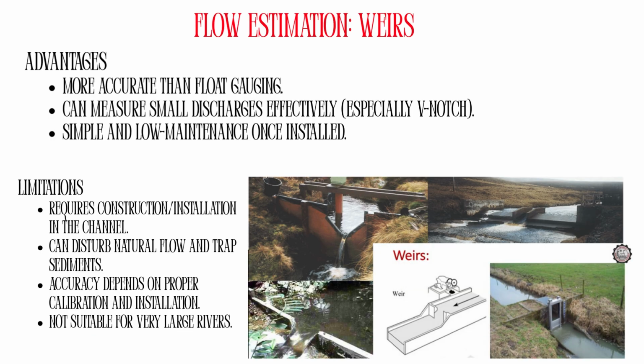Advantages: 1. More accurate than float gauging. 2. Can measure small discharges effectively, especially V-notch. 3. Simple and low maintenance once installed.